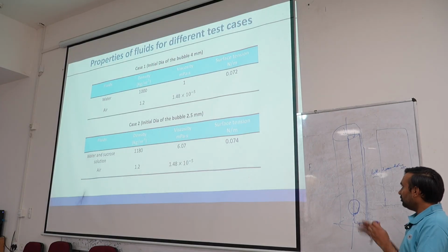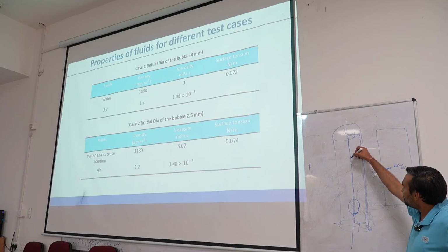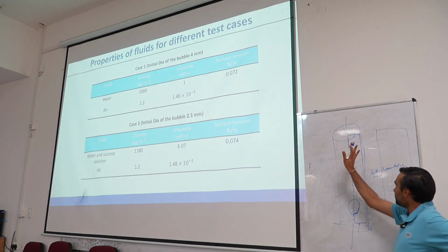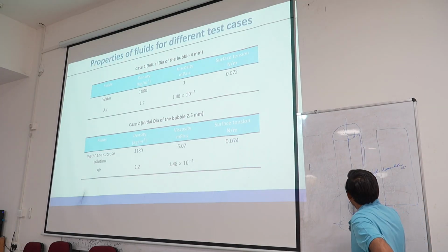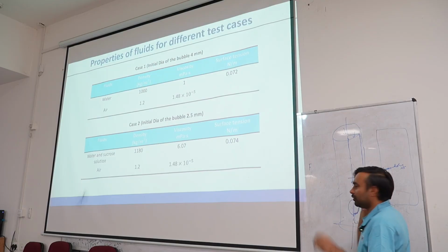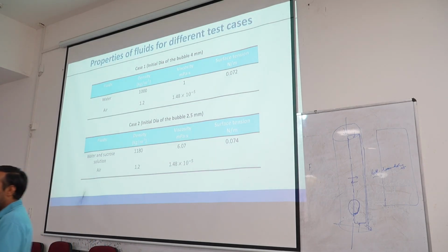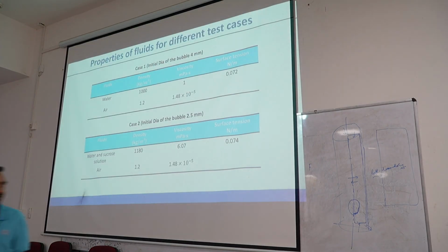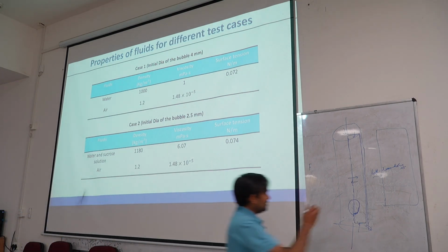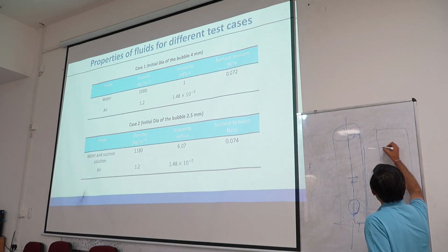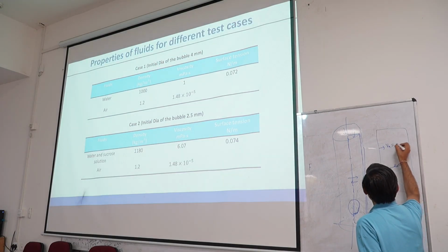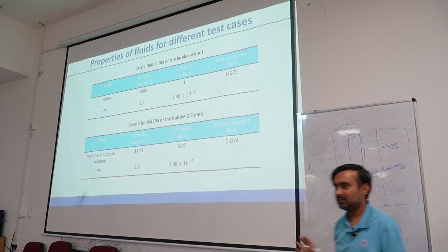So, what we need to do for this particular boundary, we need to specify the appropriate boundary conditions. Okay. The situation will be symmetric only when no flow can cross the axis of the pipe. Is this point clear? If there is crossing of the flow across the axis of the pipe, then the situation cannot be symmetric about its axis. So, one point is very clear, that at this boundary the normal component of the velocity has to be equal to 0.